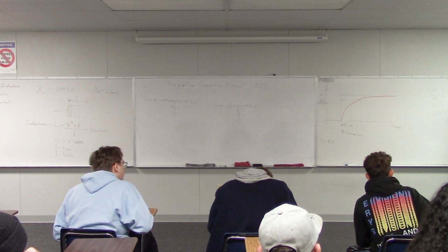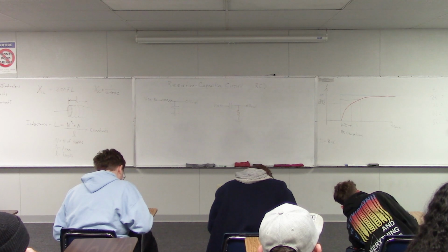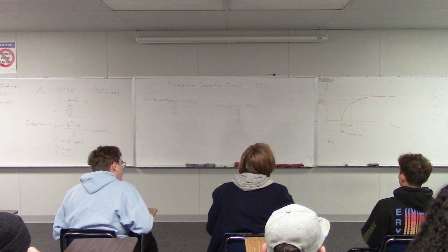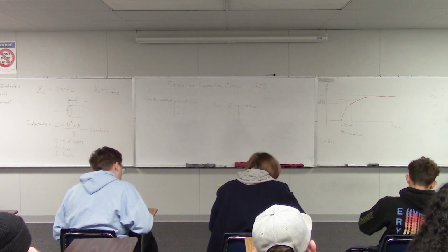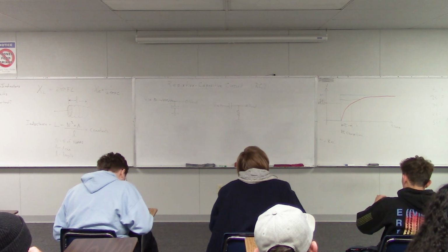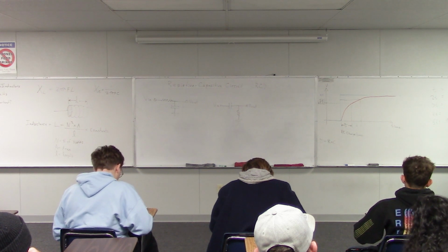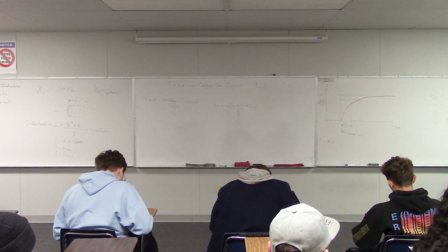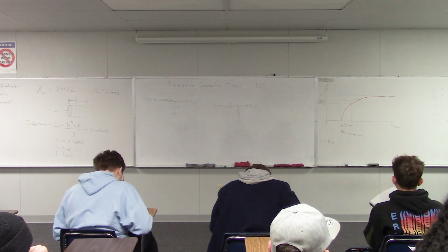And so people have tossed this around for a while, and they said that at 99.3%, you know, that's less than 1% away from fully charged. We're going to call that good enough. So 5 time constants is often used as a good approximation. We say that 5 time constants is about fully charged. Even though it might not be completely 100% there, it's pretty close.